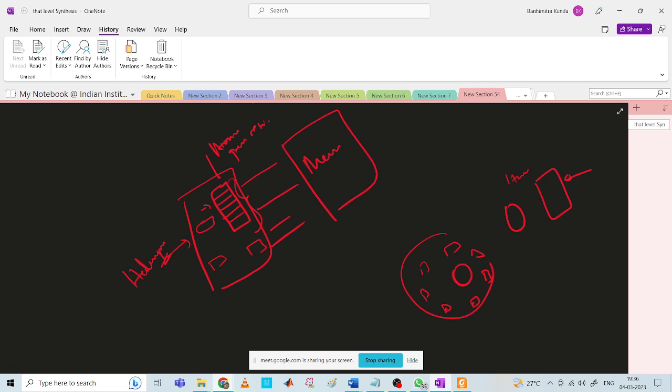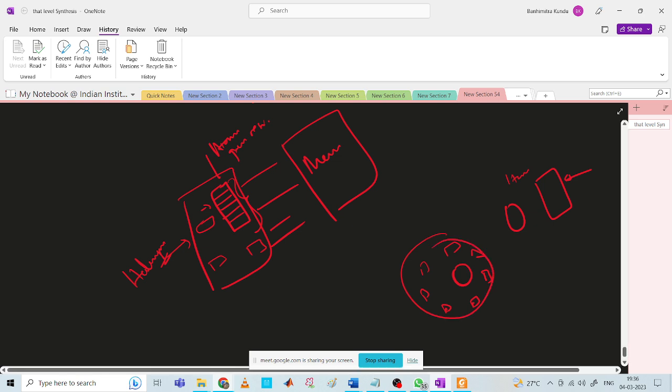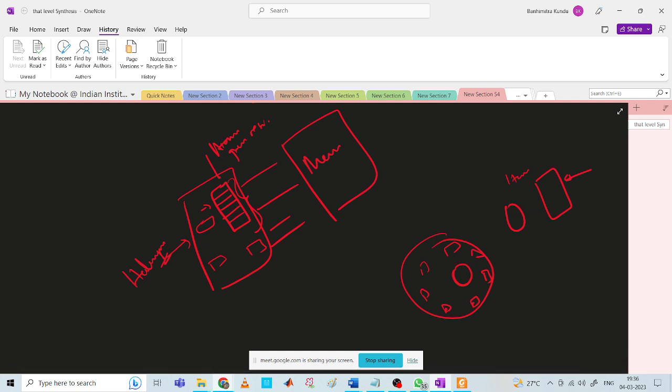But when it is scattered, it is near the processor, so you will not have any timing issue. At the same time, you will have all the registers near the core. So these are basically registers scattered throughout the die of the processor, and these are called heterogeneous registers.